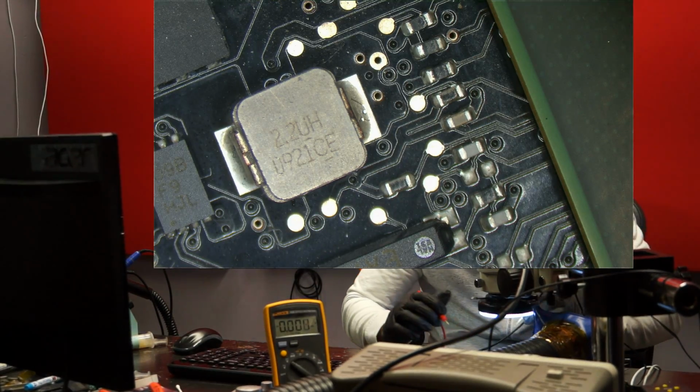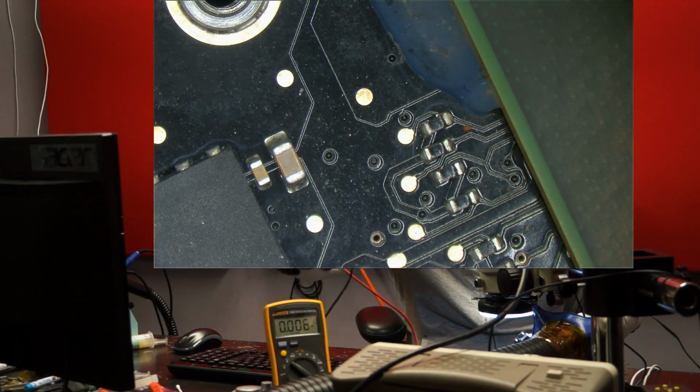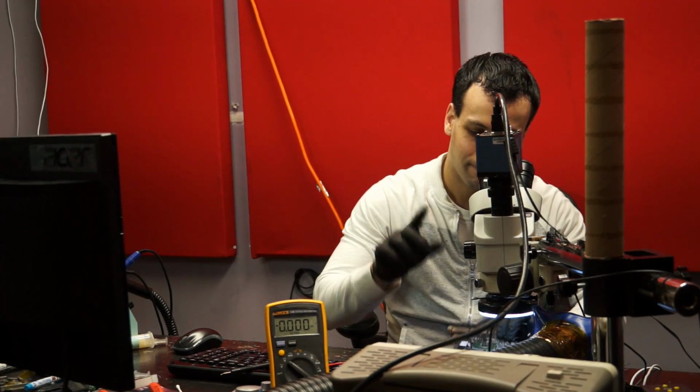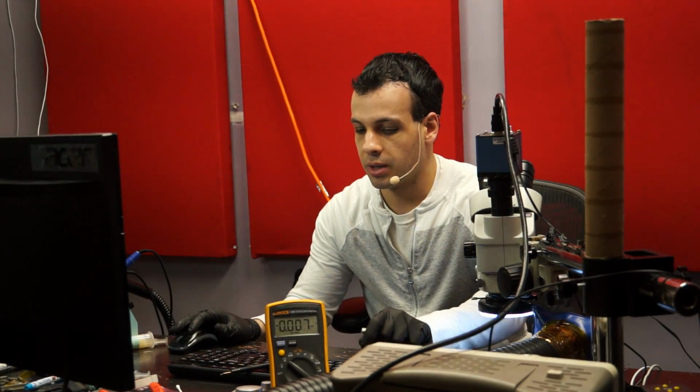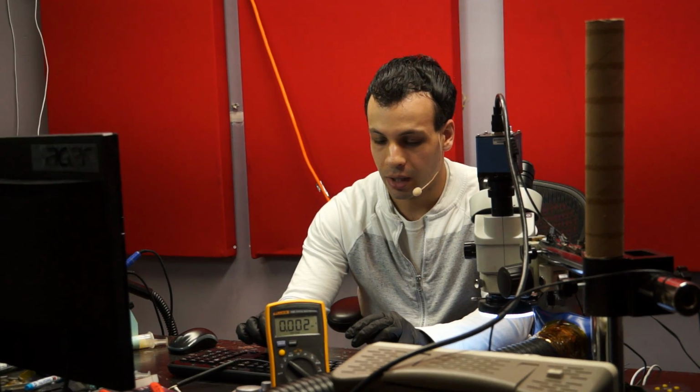And we have 1.9. So even though I measured PP3V3S5, here's the thing. I measured PP3V3S5 just a minute ago, and it measured what it was supposed to. Now it doesn't. All right, now we're getting closer here. Now let's measure around the IC responsible for PP3V3S5. This is the stuff that's going to get new people. You measured it a minute ago and it worked, and now you measured it and it didn't.